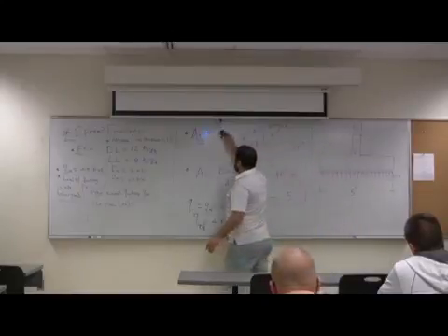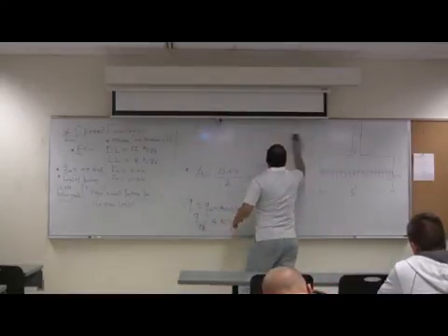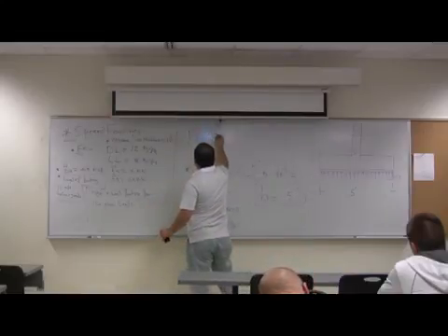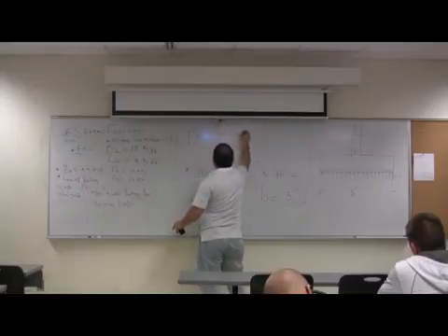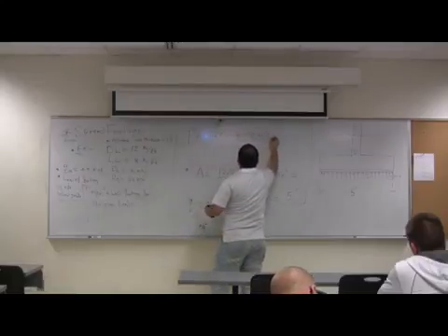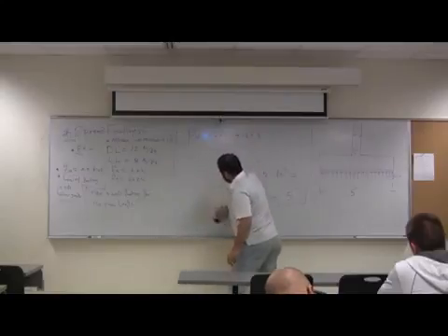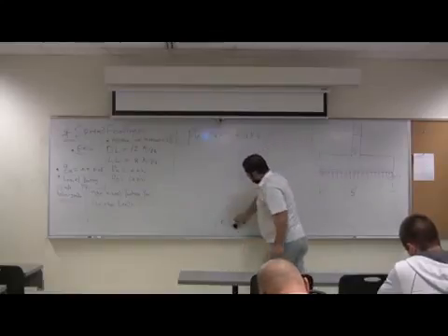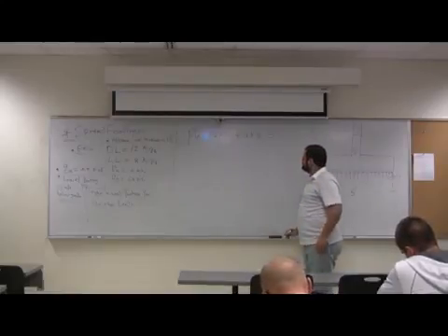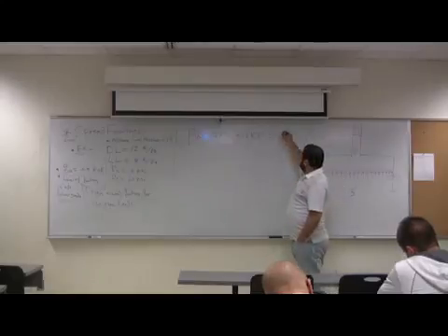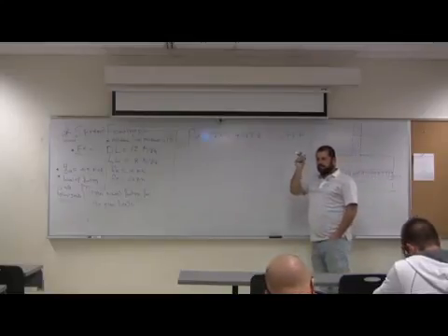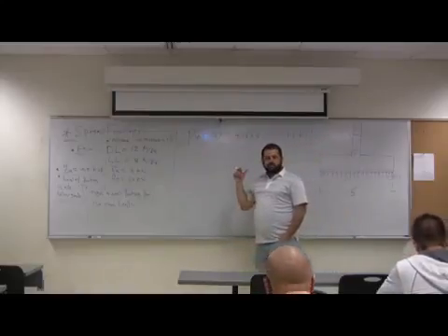Once you have something like that, after that, what do you do? Ultimate load. So P ultimate equals what? 1.2 times 12 plus 1.6 times 8. What do you get? 27.2 kips per foot. We know that everything is per foot. We are designing a 1 foot strip of the wall footing.